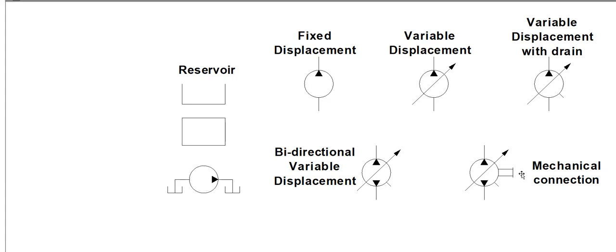They might have a picture of the engine or a box that's labeled engine, so you know it's an engine driven pump, or they could have it on gears inside a gearbox and a transmission, indicating that the pump is driven off of the transmission. Nonetheless, anytime you have this double line and symbol on the side of this pump, that double line is going to indicate a mechanical connection. We're going to see that double line coming back again when we get into other directional control valves. We're going to see other mechanical connections look the same way. So just take note of that.